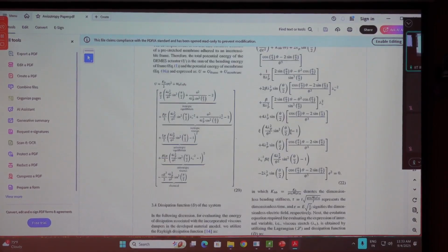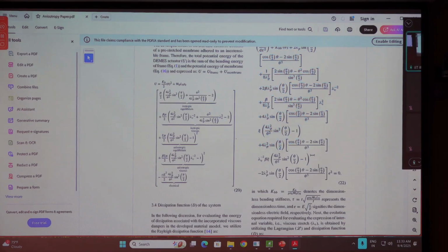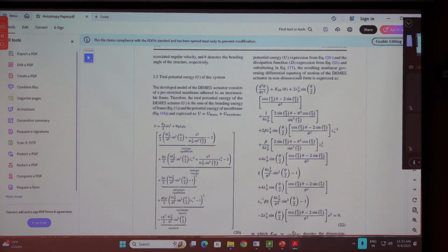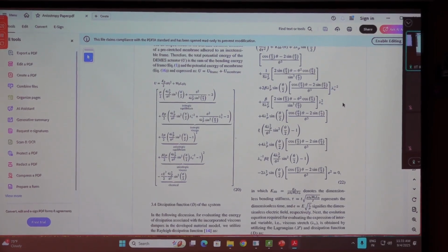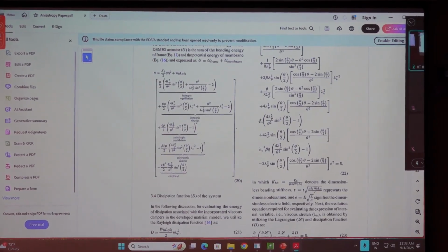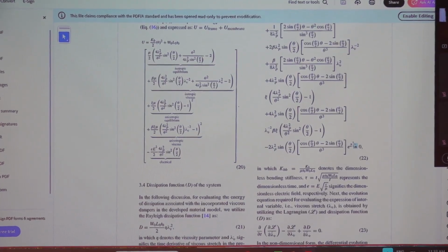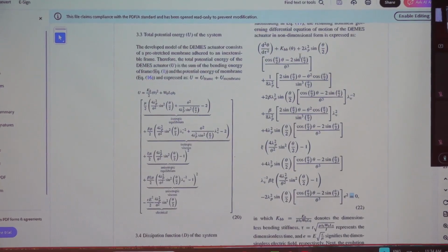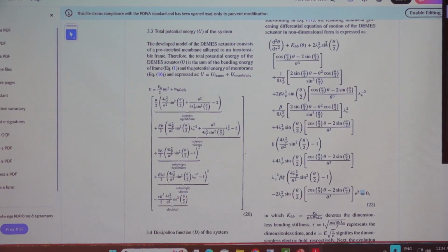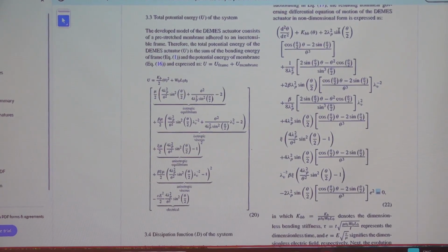By solving this, you will first get a very, very complicated non-linear governing dynamic equation of motion of this DE actuator. It will have the viscous effect term, that is lambda viscous, and a proportionality constant; lambda viscous is the internal variable. It will have the anisotropy parameter xi, and an electrical effect, that is the E term. Why is it coming? Because we are considering the membrane to be a visco-anisotropic membrane, and lambda p is also there, the pre-stretch. We have initially provided the pre-stretch also. So this is an aniso-visco-hyperelastic membrane, we can see.